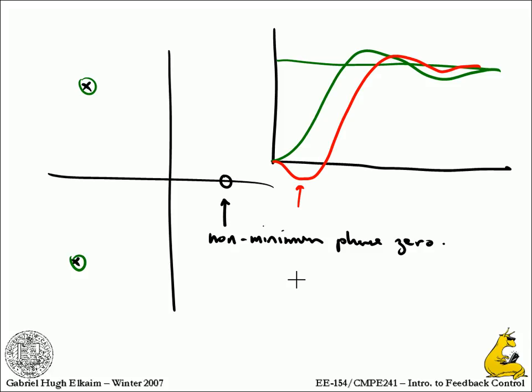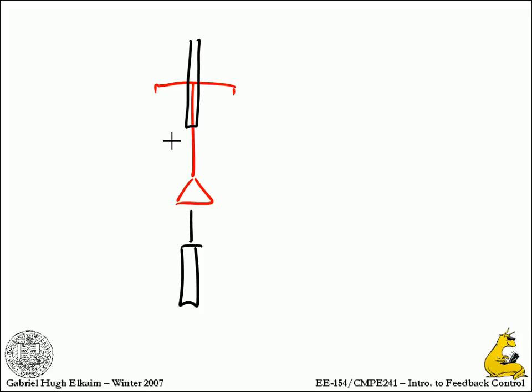What? No. Yeah. Absolutely. You're riding. So, let's push the right handlebar. Okay, the bicycle experiment. So here, you have to actually go like this. You can think of turning left, but it actually turns the other way. So, here's your bicycle, looking from the top down. So, you're going at speed. Obviously, it doesn't work if you're not traveling at any speed. But if you take your finger and you push this way on the handlebar, all right, the bike is going to take a path that way. You push away from it, you will turn into that direction. Absolutely.